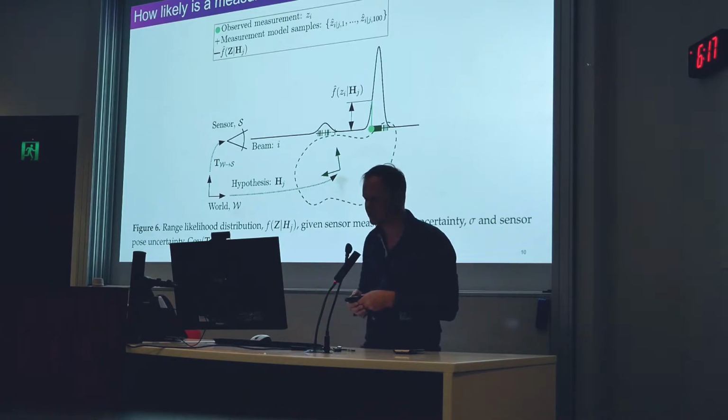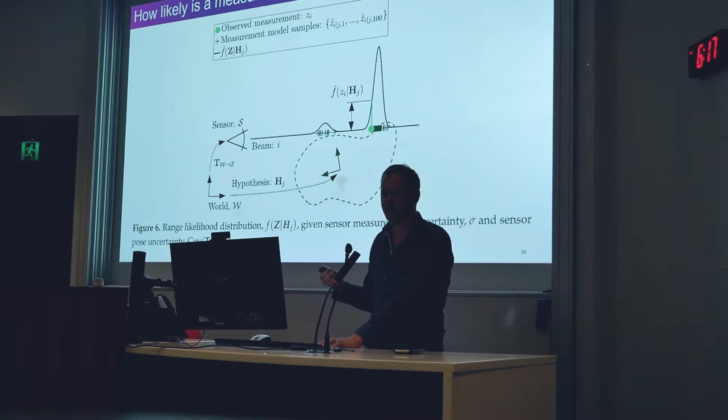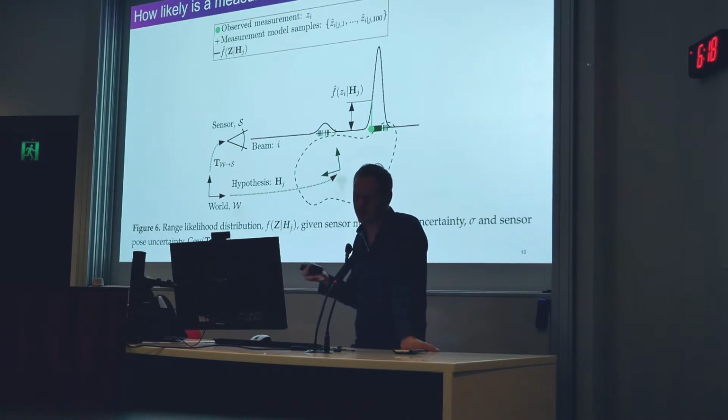If I was to perturb that frame transform, if I was to sample some errors, we'll say 10 millimetre errors on position, 10 milliradian errors on rotations, add them in, relocate the sensor, and then raycast again, I'd get all these little other measurements.